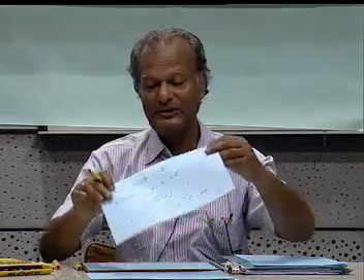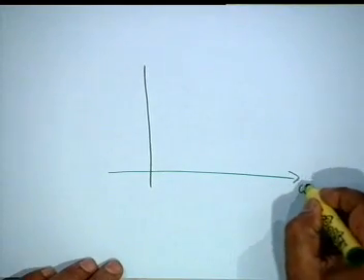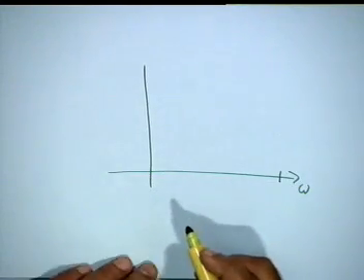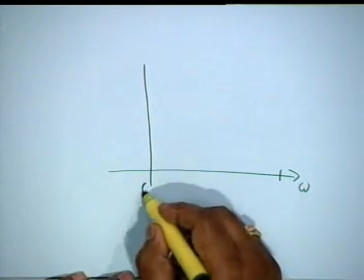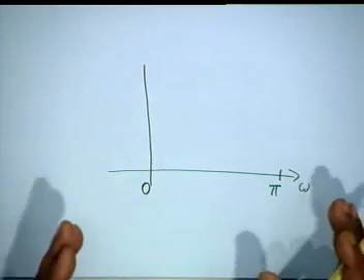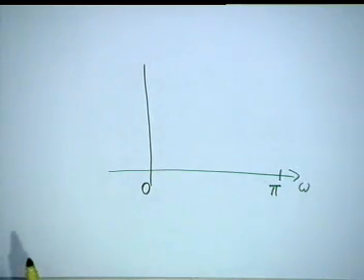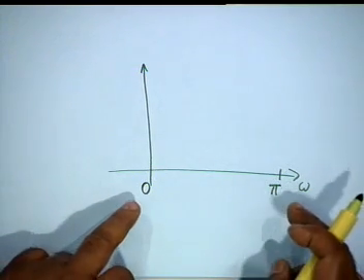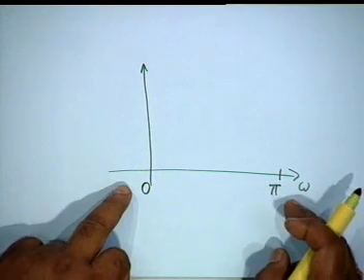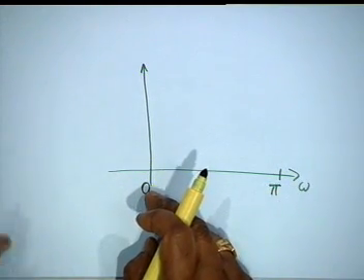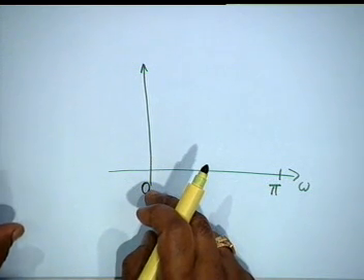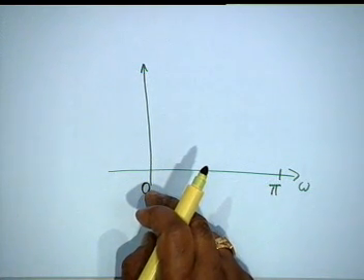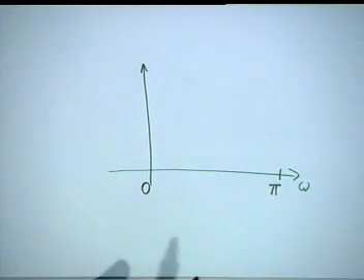So, what we can realize for a low pass filter, for example, our range of vision fortunately in digital signal processing is 0 to pi. We have a finite range of vision, and when we are considering magnitude or phase, it suffices to consider only the positive frequencies, because we know for negative frequencies the magnitude is even and the angle is odd. Therefore, if we know this part, we know the other part also.